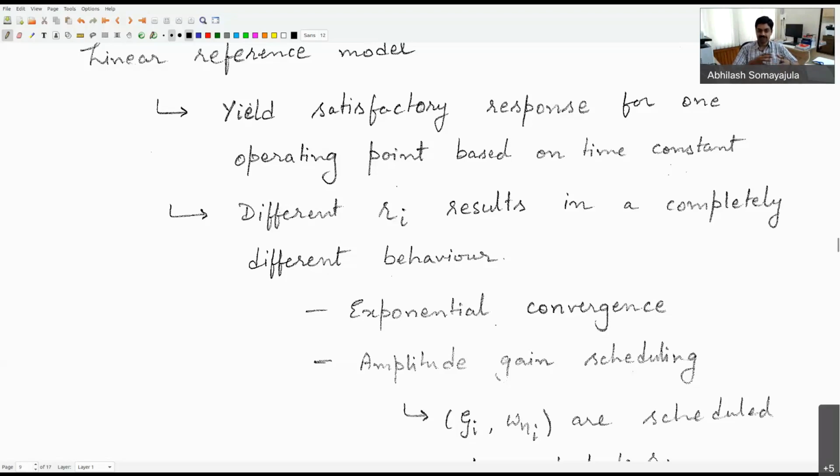Right? So when we design these so-called guidance systems, the linear system works well, but it doesn't have any bounds. If I give a much higher amplitude on the joystick, it may result in a much higher amplitude in the velocities, which may not be physically possible. So I have to scale back. When we start to understand this sort of behavior, we may need to adjust the so-called weights of our filters depending on how high the amplitude is.